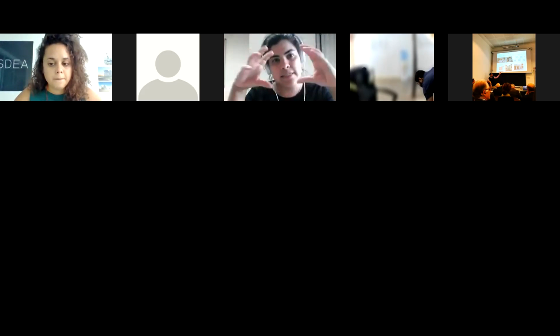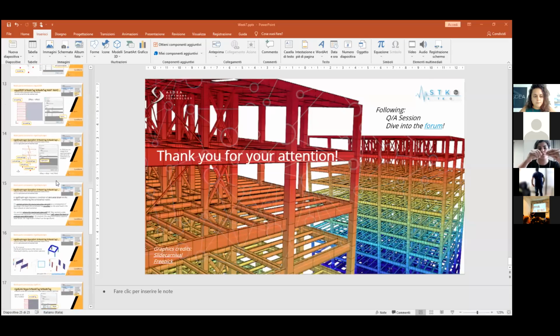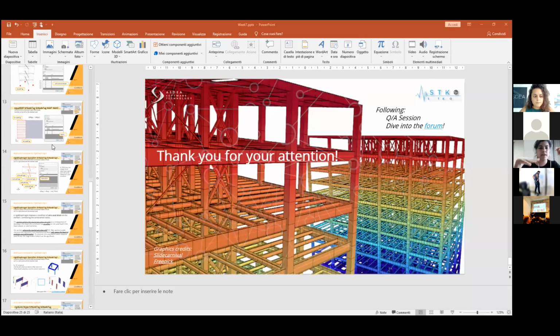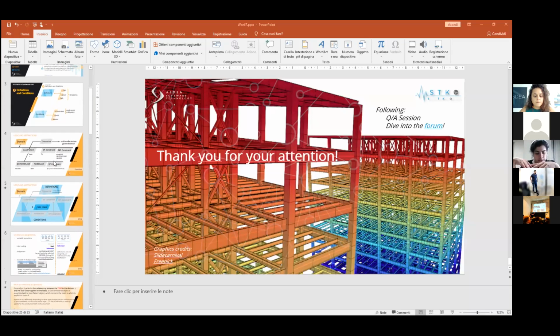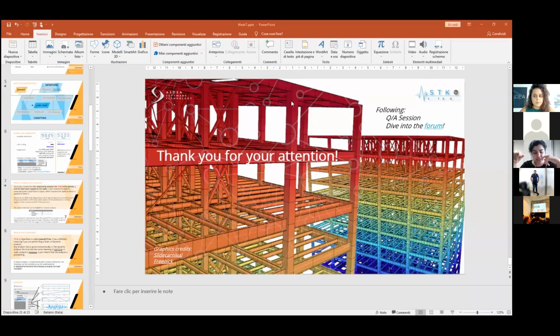In the case, for example, of 2 stages where I apply the vertical load and then do a pushover, even if I'm not doing a displacement control, I have to keep the load constant and reset the pseudo time? Yes, I'm just doing a regular pushover, not in displacement control.